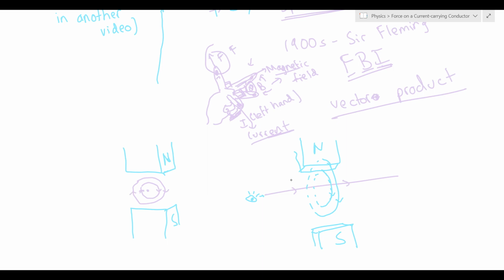So yeah, in this case, the magnetic field due to the wire is something like that. And due to the magnets, we know it's something like this. And so what you see is in this region over here, that is in front of the wire, if we're looking at it from here, the magnetic field lines are in the same direction due to both sources, so they're going to add and we're going to have a stronger field over here, or more magnetic flux density over here. However, in this region the direction of the two fields is opposite, and so they're going to cancel out and we're going to have a weaker field or lower magnetic flux density.